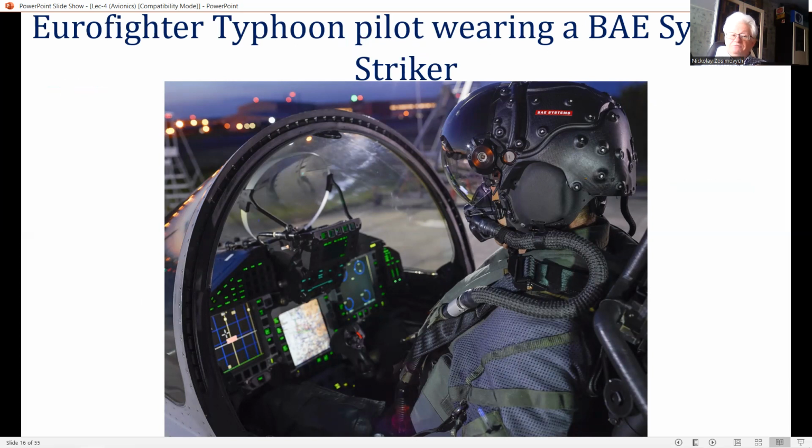The pilot's line of sight with respect to the airplane axis has to be inferred by the head tracker, and accuracy on the boresight and in the principal region of the head motion box is better than 2 milliradians.